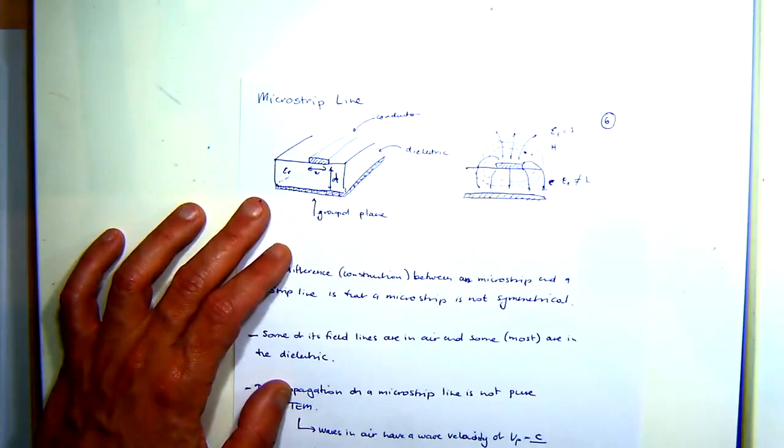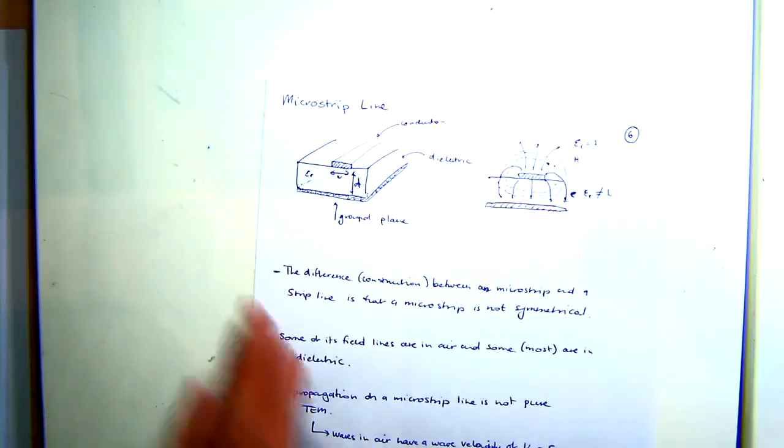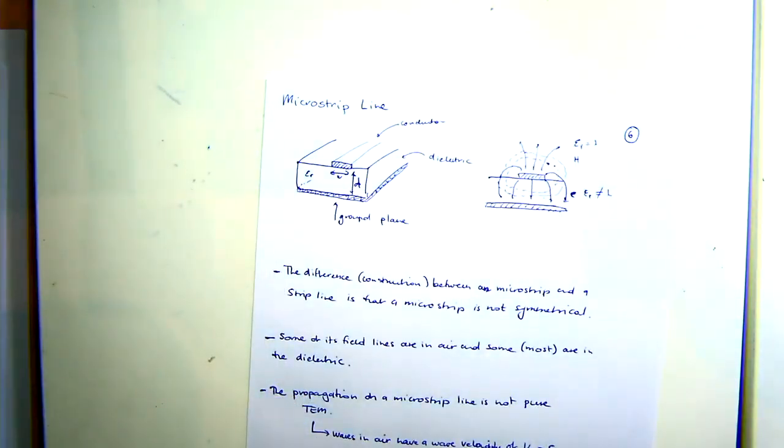Yes? So let's say we use this in a PCB. Isn't it dangerous to just let the electric field go over the PCB rather than being condensed? But sometimes you don't have a choice. You might need to connect to something, and sometimes it's not necessarily dangerous, but it's not ideal. Sometimes you've only got one layer, the top layer, that you want to route on, or your manager says, I want this to be 50 cents. I don't care, yes, you'll get worse performance, but I only want a 2-layer PCB board. And you've got no choice, right?